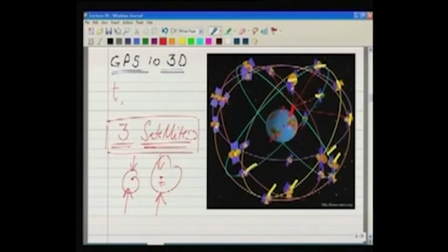So here in this coordinate system, because we know the coordinates of the satellites, and by measuring these distances and doing the solution the way we are doing, we can determine this particular point. One more thing here: because we can eliminate one point in that case, 3 satellites are good enough, but we would like to go for more satellites, because we know redundancy is always desirable.